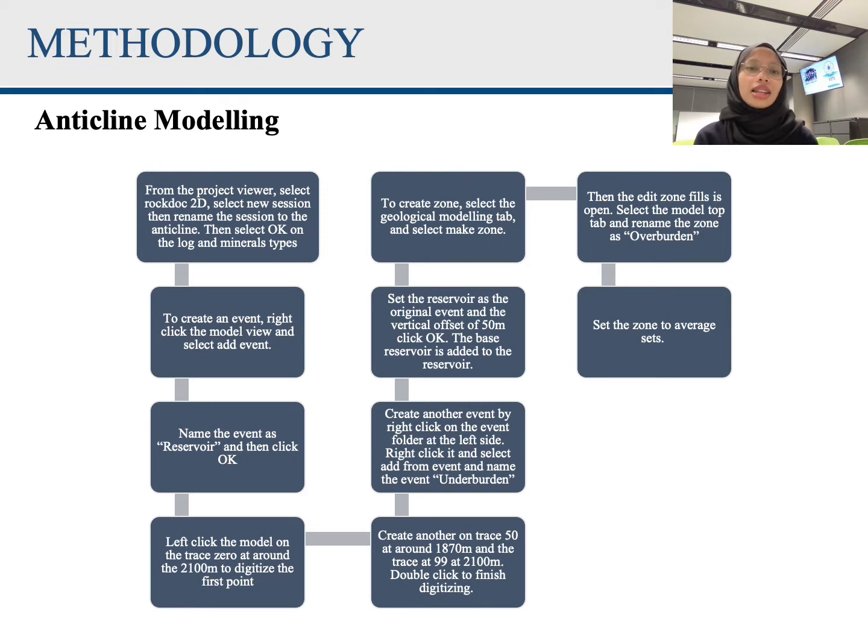To create zone, select the Geological Modeling tab and select Make Zone. Then the Edit Zone fields is open. Select the Model Top tab and rename the zone as Overburden. And set the zone to average set.